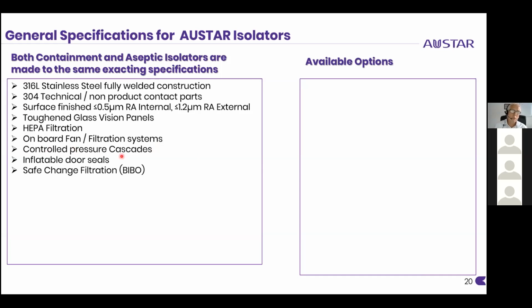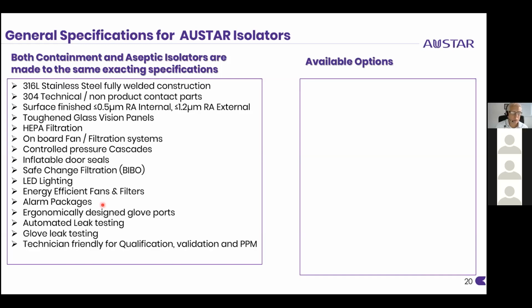Inflatable door seals, so we've no leakage out of the system, and also to protect service engineers, we can put on board bag in, bag out filtration. So when it's time to change the filters, any dangerous product that's on those filters, we can also protect the technicians that change the filters. LED lighting, energy efficient fans, and also energy efficient filters on the market now. We also have alarm packages to show whenever there's any operations out of design parameters.